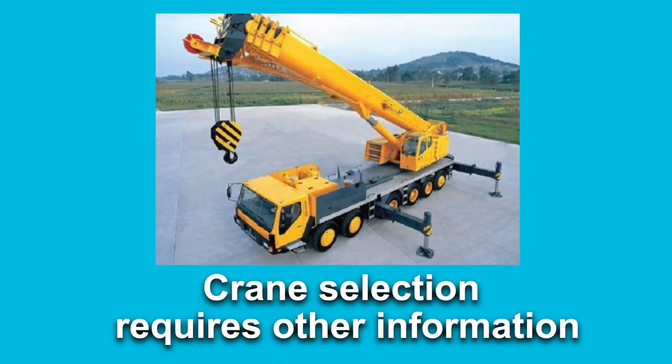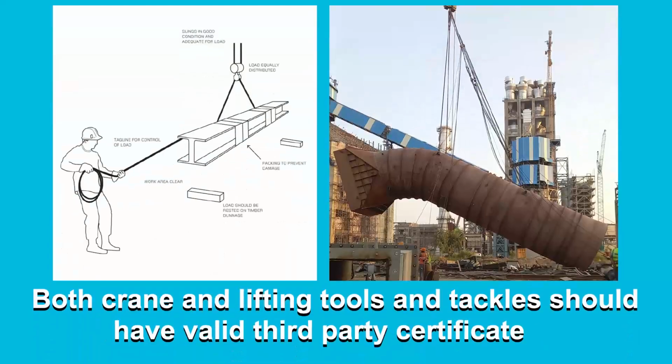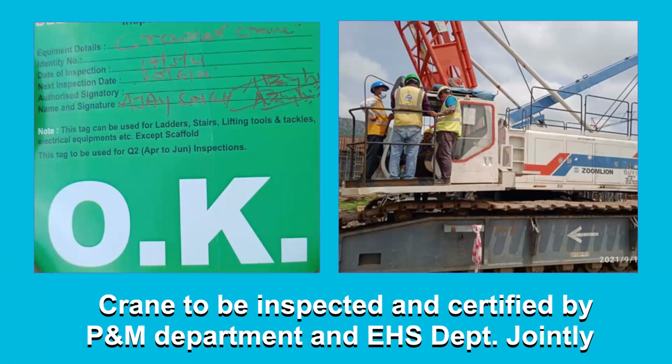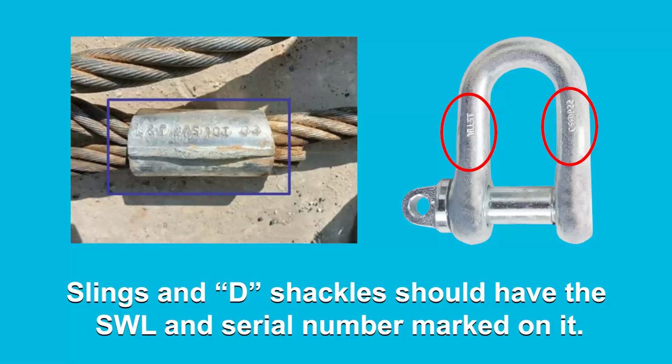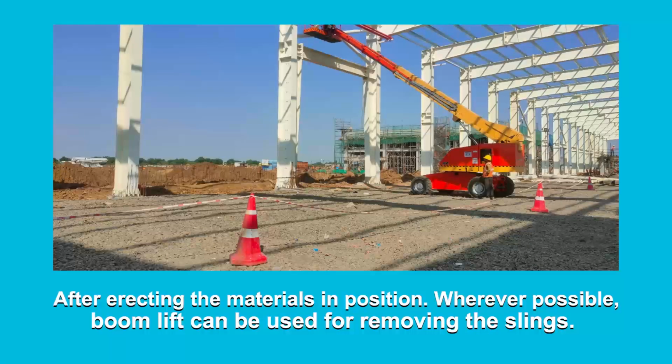Crane selection requires other information like radius and height of the location where the material is to be erected. Both crane and lifting tools and tackles should have valid third-party certificate. Crane to be inspected and certified by P&M department and EHS department jointly. Slings and D-shackles should have the SWL and serial number marked on it. Before erection, we need to make the access and working platform along with fall arrestor and lifeline to climb and remove the slings after erecting the materials in position.